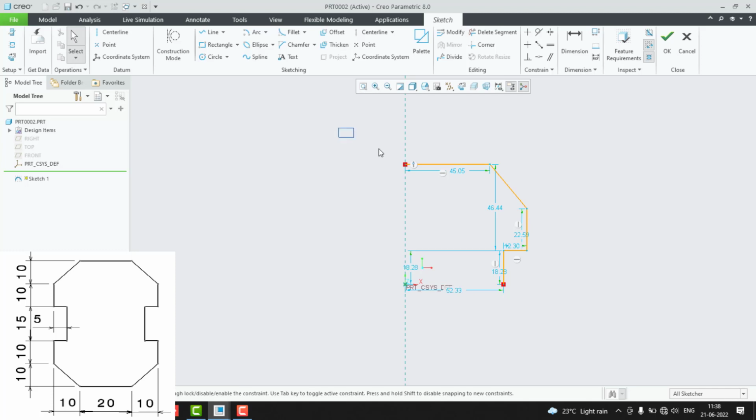So here you can select the point to mirror. If I just select and hold the sketch, mirroring with the point is not possible, so what you can do is draw a line again, select. If I make the reference as well, it doesn't work, I think. Yeah, even reference access will not help you to do this.